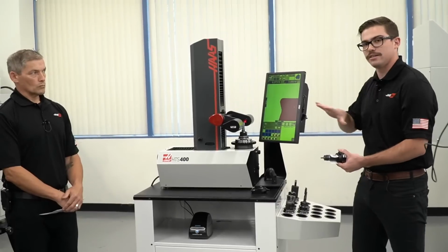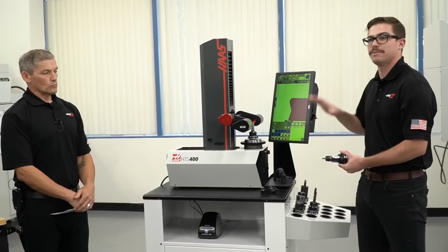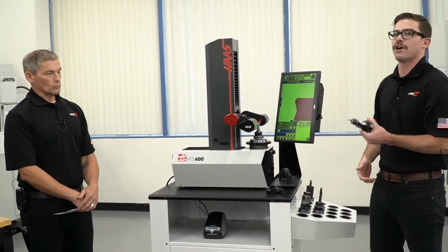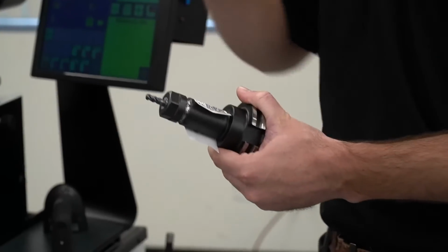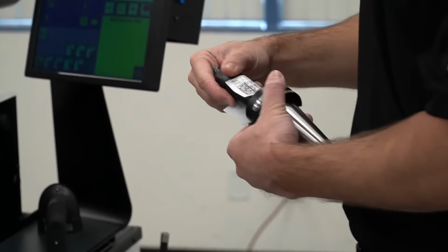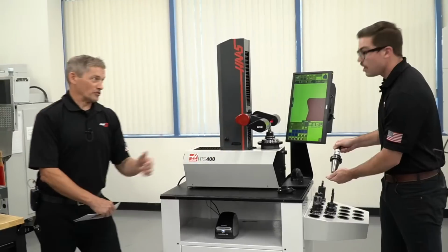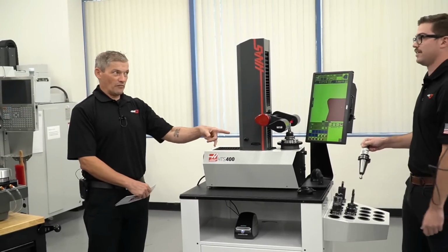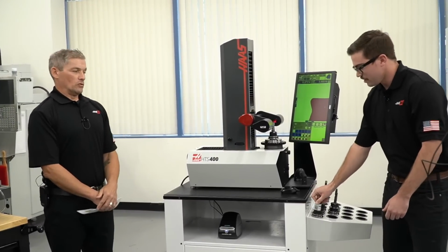I can go ahead and measure all my tools, put labels on them, set them aside, and when I need it, I can grab my tool, scan it in, put it in the spindle, and I'm back up and running. You also have an indication that you've done that tool. It's just a visible indicator that I've measured that tool. Exactly. Cool. That sounds great.